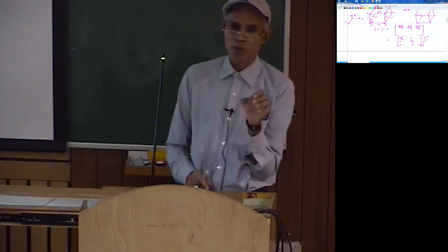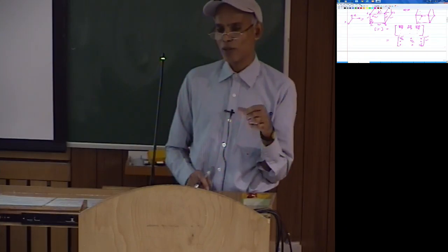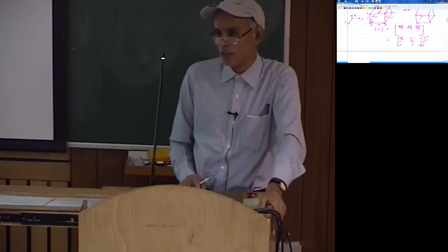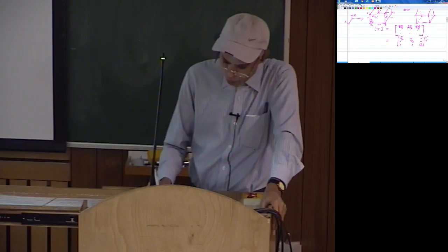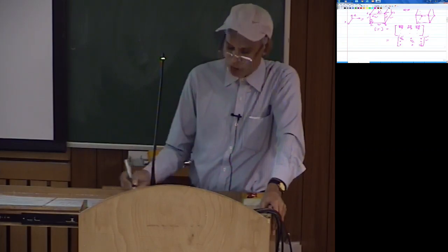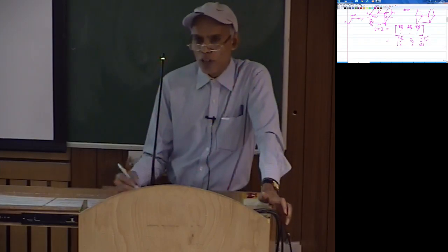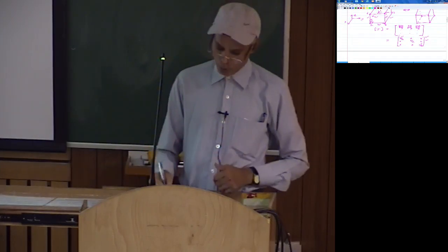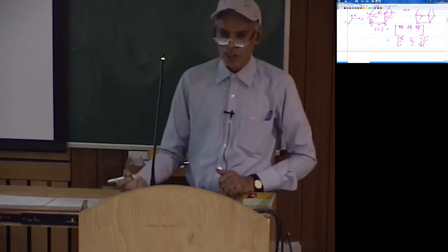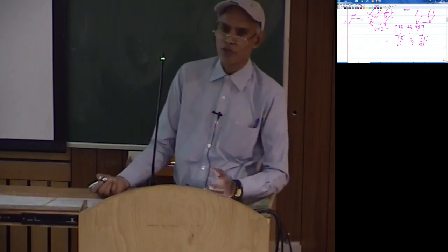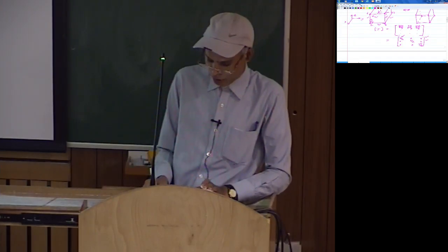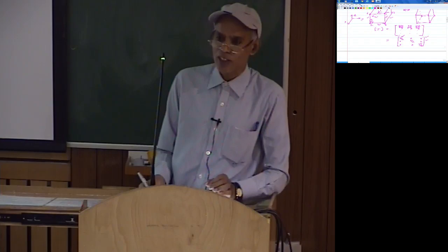It is not possible to decide the number of elements on the basis of the smallest dimension, because then the number of elements would go to a very large number. So what is allowed is a maximum ratio of 10 between any of these dimensions. You can have one edge length 10, C can be 1, and B in between. This ratio of the edge lengths is known as the aspect ratio.